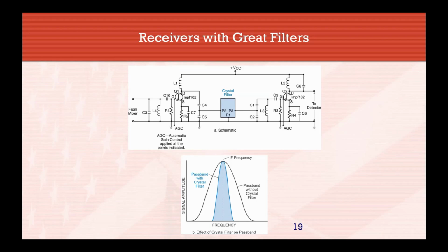If you look at that, we want to tap the signal off of Q1, coming off the drain side of Q1. The signal's coming out, going through C4 and into the crystal filter. Now, we put that other little capacitor C5 there to swamp out or take out any of the unwanted signal that we can, so that just the best part of the signal we're looking for goes to P2. And then the same is true coming out. There's an additional factor for that, however. You'll notice the drain is connected, as you go up to the top of the diagram, to VCC, that is the positive voltage source.